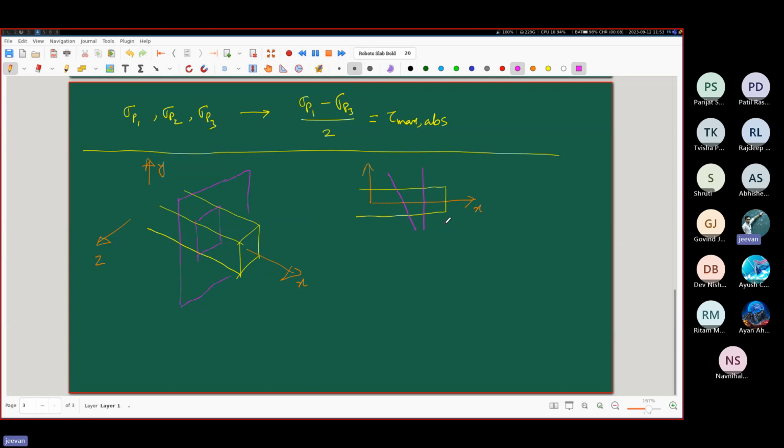Okay, in fact, you can obtain these kinds of transformations as a function of x, y, and z. So you can obtain an overall picture of the maximum possible values and the minimum possible values of the stresses at each and every point over this beam. Of course, you cannot do such a thing by hand, you have to do it programmatically, but the foundational basis of all such things is certainly what we have been discussing in this chapter. So for the design of beams and shafts, this transformation of stresses is an absolutely foundationally important thing.